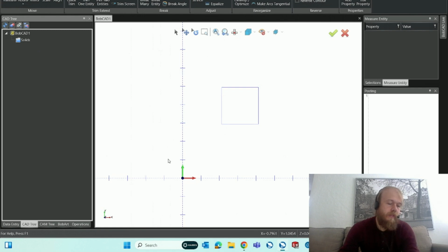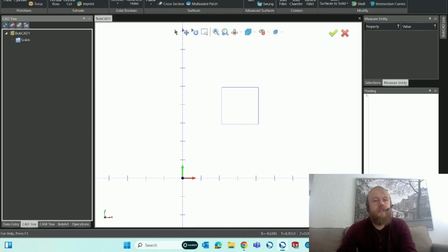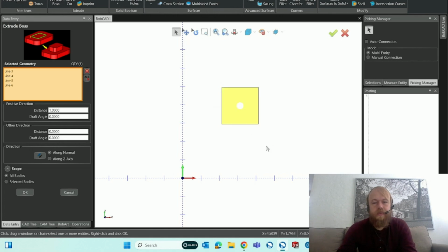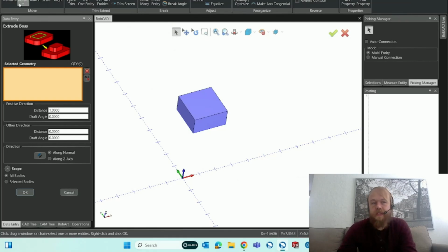We'll go into some of the options from any of the older versions into V37 that can be really useful. We'll take a look at basically just the new user interface here. This was a jump from version 30 to the newer versions. You can see this ribbon bar layout up at the top. You can see our home page, Create 2D, where we have our 2D drawing options here. Create 3D for our extrude boss and our extrude cut to create a 3D model. We have our utilities, again, to translate, rotate, mirror the drawing. Some newer options are scaling and align.